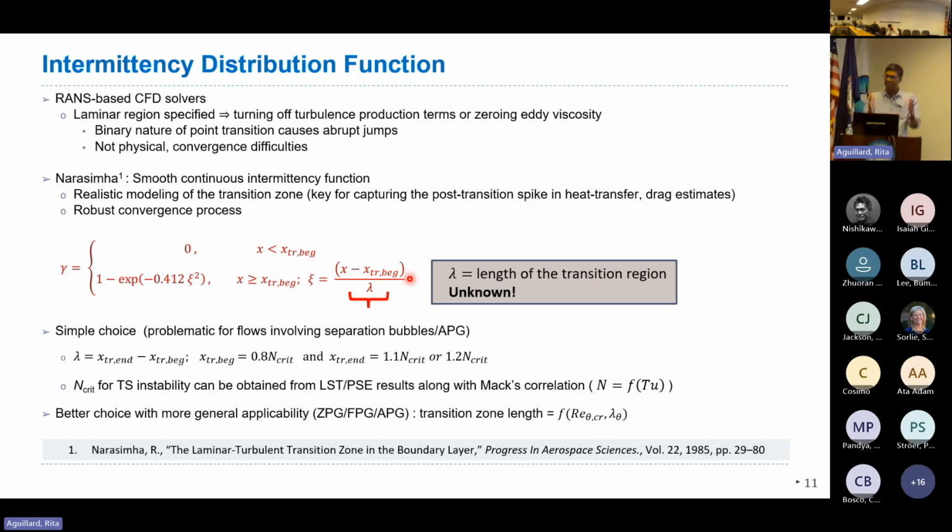And that can have a significant impact. If you have a separation bubble zone, then the transition happens immediately, very quickly. So usually you don't have too much of a length, so there the length doesn't matter. But if you have a long bubble, or a range over which the pressure gradients are kicking in, then you might end up with a long layer.